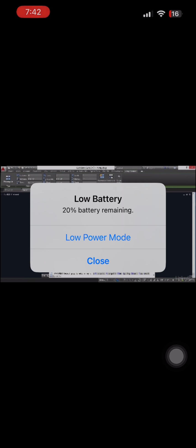You might need to zoom out to see what's happened. A default array has been generated. Notice that there's a green line around this whole tab. This is a temporary tab. It only exists while you're creating the array. We can set a number of columns and a number of rows. In this case, I just want to have 3 chairs along the edge of the desk. So I need to have 3 columns.